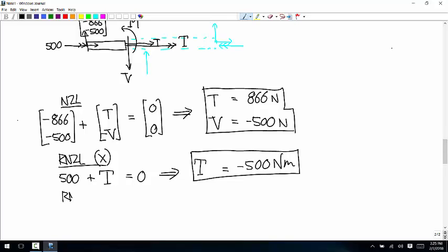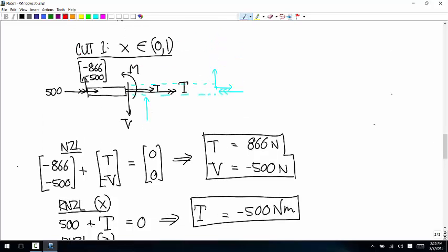And then the moment equation about the z-axis. Always going to use the left end as the about point. So nothing happening at the left end produces a moment. The tension doesn't produce a moment. The torque doesn't produce a moment about the z-axis. So the only things that matter are this M, and that's a couple, so it's just added on, and this V times that moment arm.